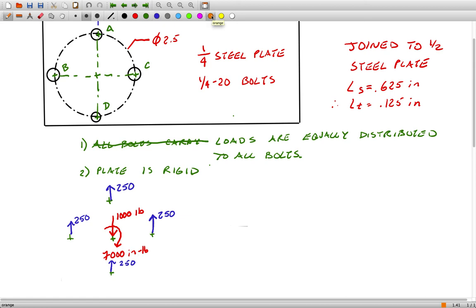And next we've got the contribution of the torque. Again, I'm going to draw it in the direction that opposes the applied torque. It's always going to be perpendicular to the radius arms as we follow along here. And this one's actually going to be upward, so it's parallel. Bring the labels down, A, B, C, and D. Now I haven't calculated the magnitude of that orange vector yet, but just looking at it, you can see at C, they're in the exact same direction, which means the full magnitude of the orange one adds to the full magnitude of the blue one. That's going to be our worst case value. We can calculate the forces at all 4.